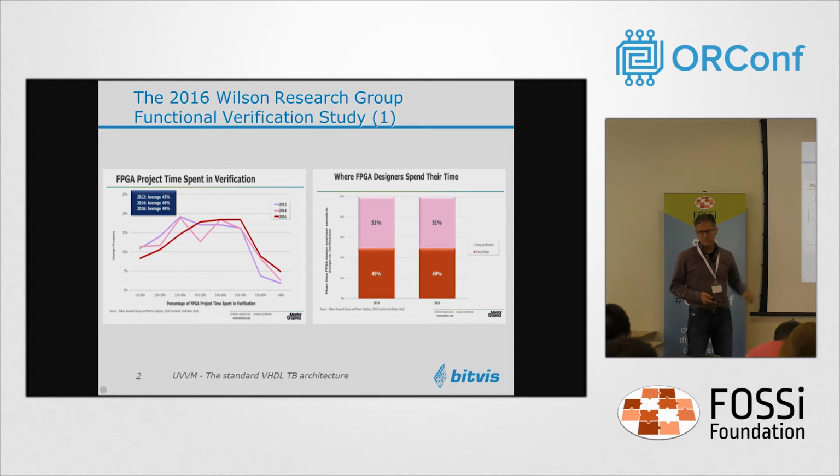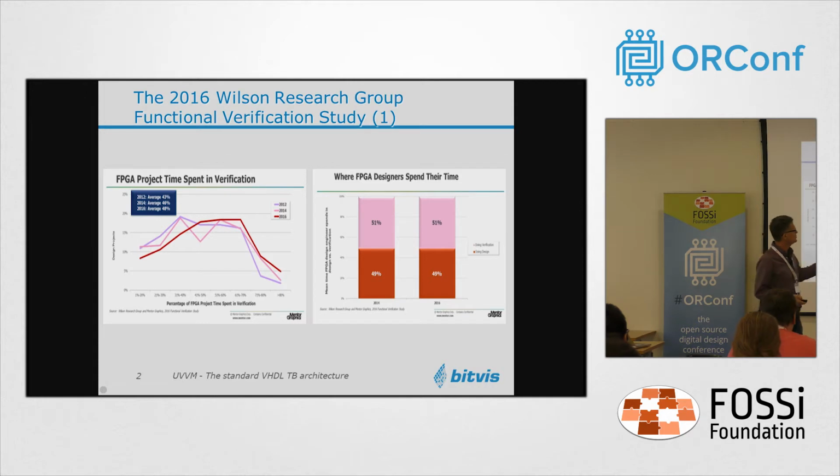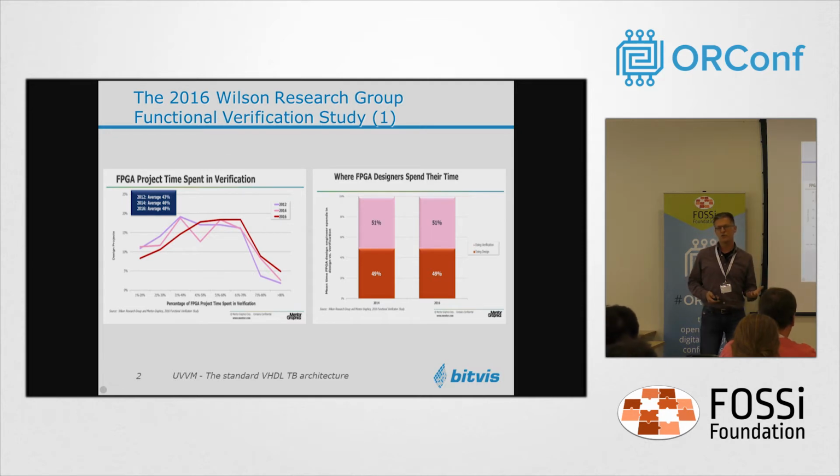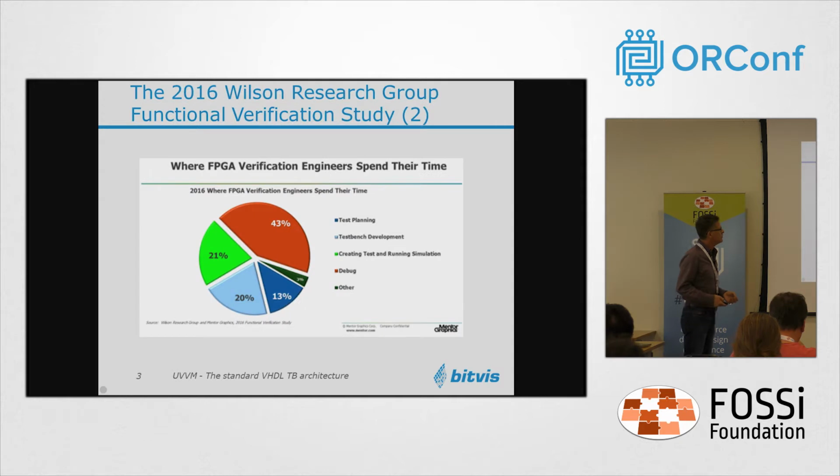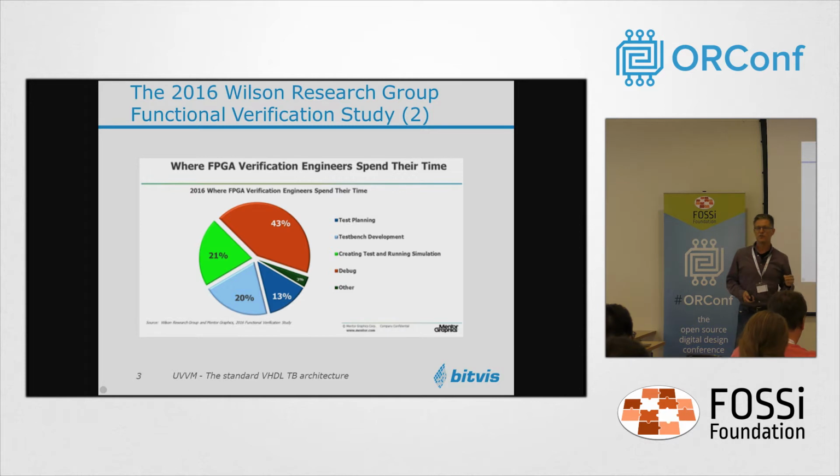Briefly, you all probably know that VHDL or FPGA verification is approximately half the time of an FPGA project on average. If you have control-oriented or protocol-oriented projects, you'll actually have more than 50% of the work being verification. But what you might not be aware of is that out of the time you spend on verification, nearly half of that is spent on debugging, debugging your design and debugging your test bench. That's extremely important. There's no focus on that.